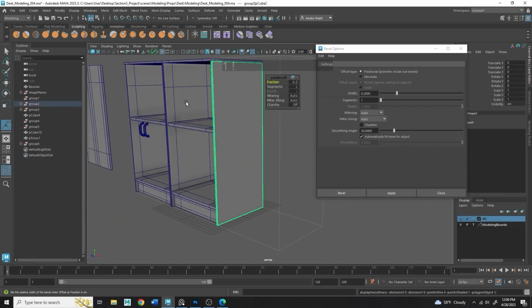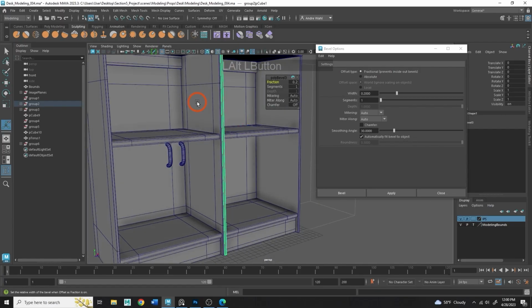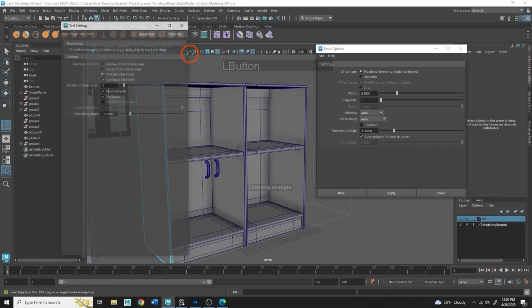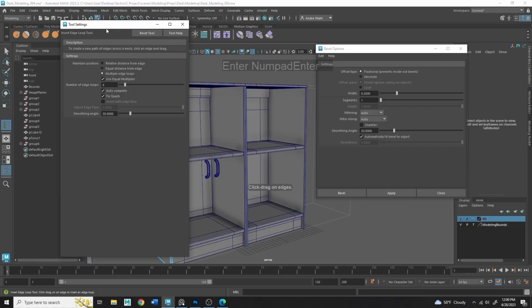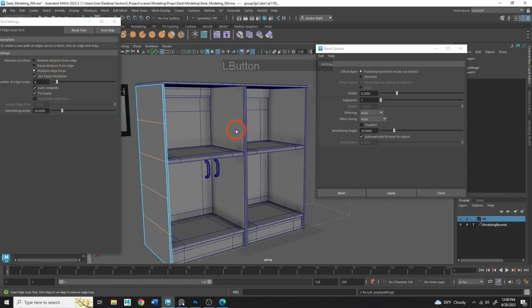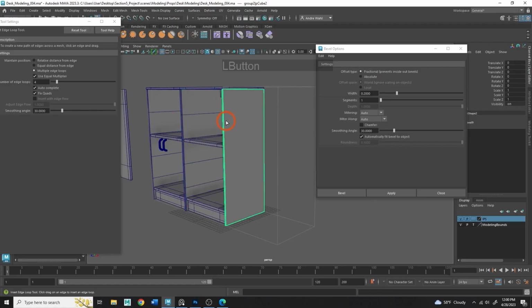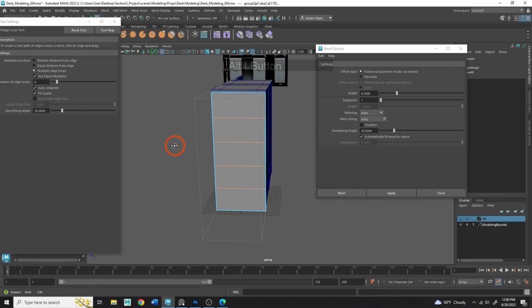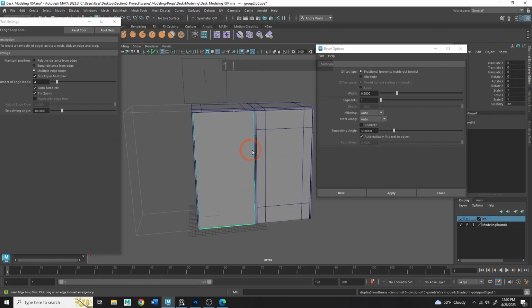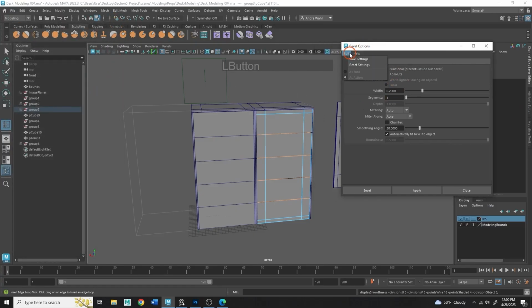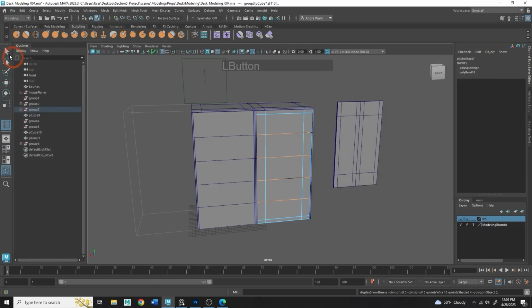Now, the stretching on these is pretty intense though. So on these side ones here, we're going to add in a couple edge loops. I think 4 should do, so I'll come into Insert Edge Loop here and just set this to a multi of 4. Remember, you have to check multi if you don't have it already. And I'm just going to come in and add these. This way, their textures don't get quite as stretched. And that should give us an okay look. And I'll do the same for the backside, especially if we're going to use anything like a cork texture or something back there. It'd be nice to have that. And I'm just going to reset this and close. And then on the bevel, I'm just going to edit, reset, and close.